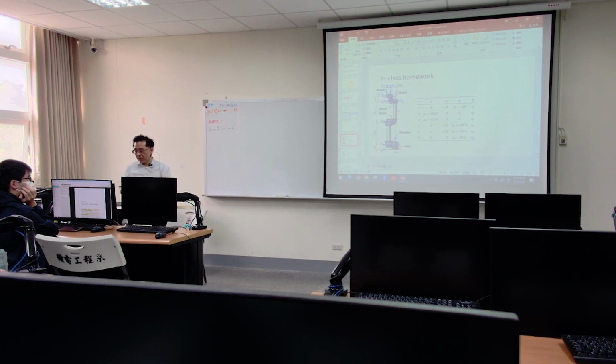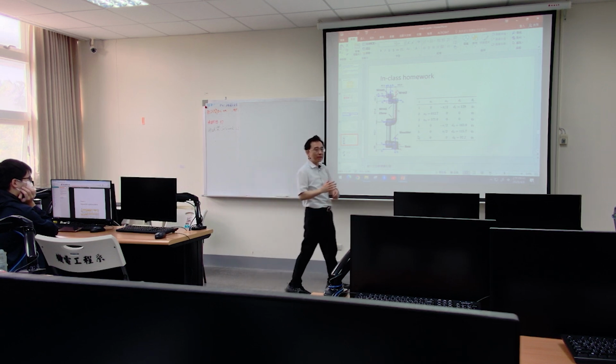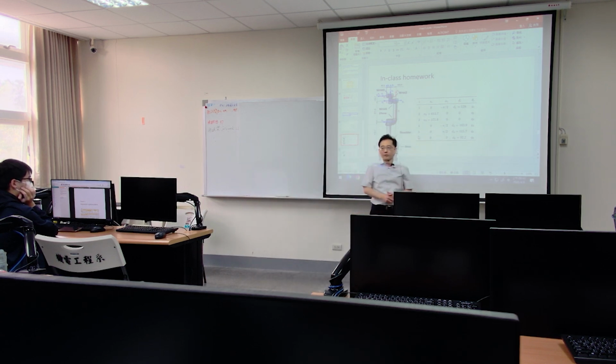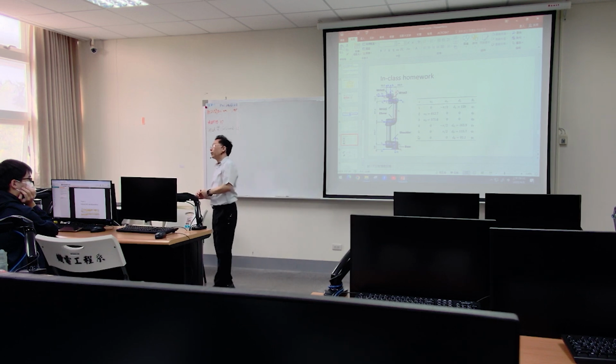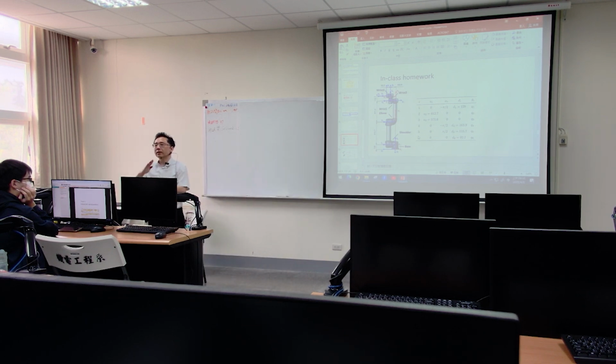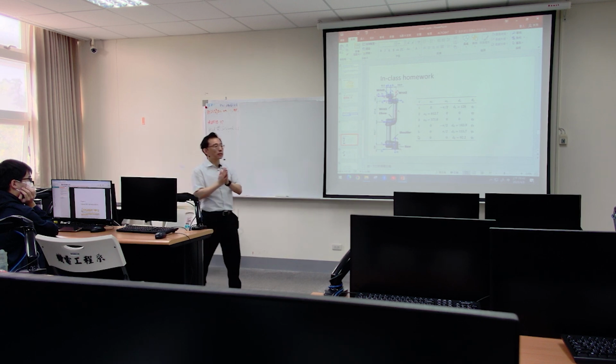Let me explain a little bit. For the joint 1, they have an alpha angle and the length d, okay? And the alpha is, I believe, what they call the twist, right? So you can observe the twist is always a negative 90 degree or positive 90 degree, because the twist angle, if you can recall, is the offset between the z and the x axis, okay?